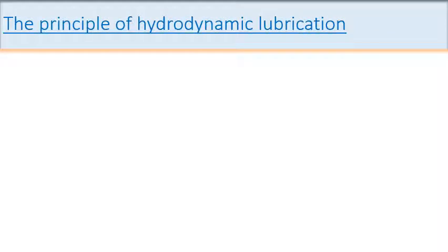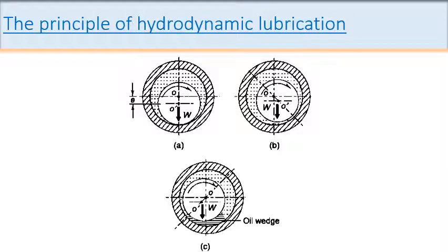Let us see the principle of hydrodynamic lubrication. As we can see from the figure, a hydrodynamic journal bearing or a full journal bearing works on the hydrodynamic principle. From figure A, we have a journal or shaft on the inside, and the outer one is the bearing, which is shown by the hatched portion.